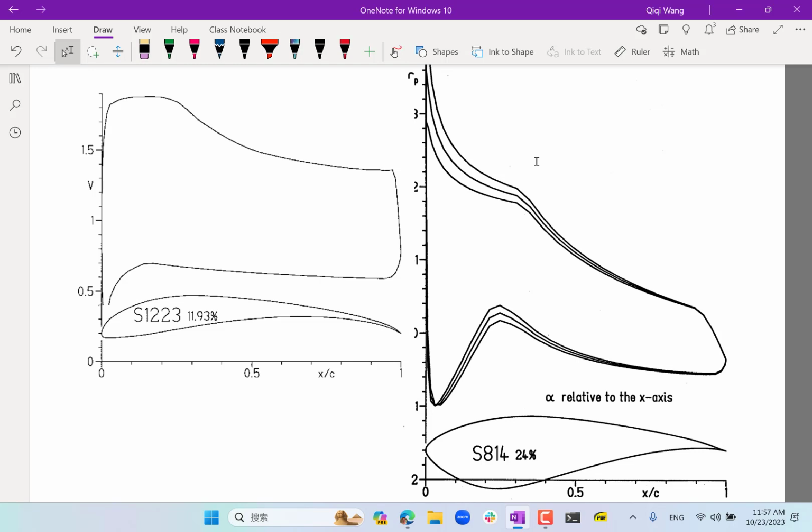Up to a point where you are sure the boundary layer has transitioned into a turbulent boundary layer. Then you make it steeper again, right? Because you know the turbulent boundary layer won't separate as easily. You have more equivalent viscous forces. But again, you need to ease it as you go towards the trailing edge, because as the turbulent boundary layer becomes thicker and thicker, even though there is turbulence, it's still easier to separate as it gets thicker, right? But you won't need as shallow a gradient as in the laminar boundary layer.